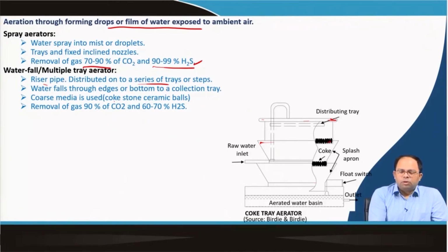Coarse media is used, coke, stones, ceramic balls, these are the different things that we can use. Removal of gas: 90% of CO2 and 60 to 70% of H2S. So, see over here CO2 could be almost removed from this particular water.